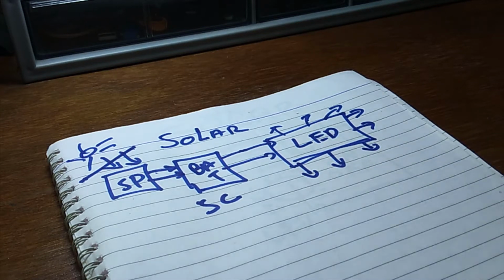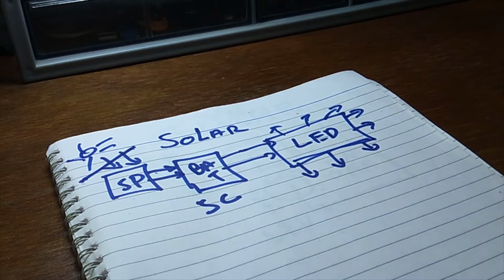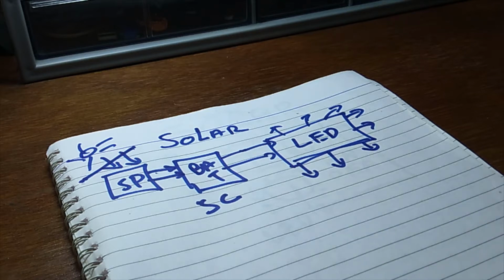Apart from that, you might have simple night lamps or night posts or even street lights which could adopt this. The circuit that I'm going to build right now on the breadboard is quite a small circuit. The solar panel is very small, and it typically generates voltages of maybe max 5 volts and maybe 1 milliamp max. That's the wattage that we are handling here. So just to show you how this can be effectively done, I'm going to use such a very small power solar panel and demonstrate the same thing to you.